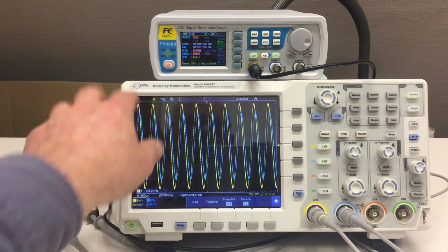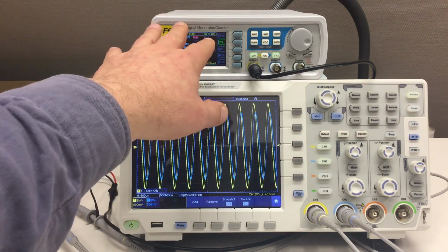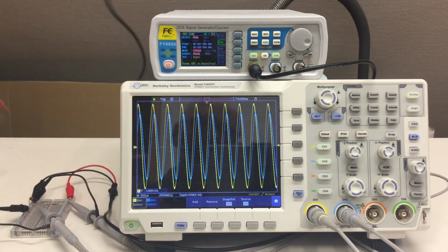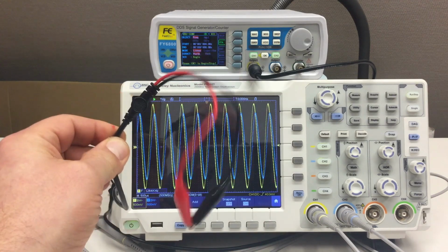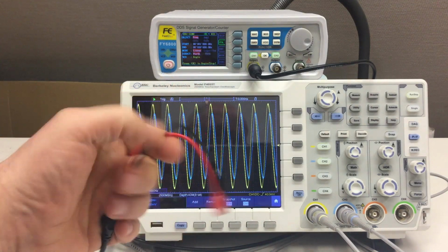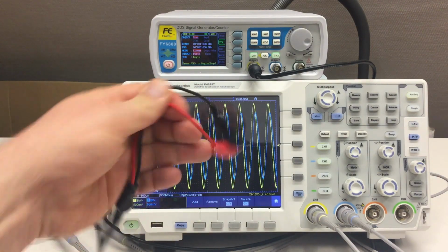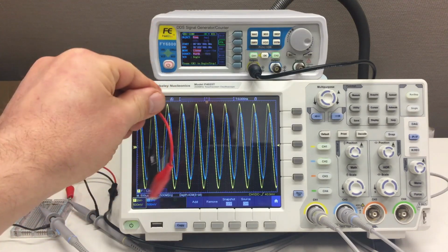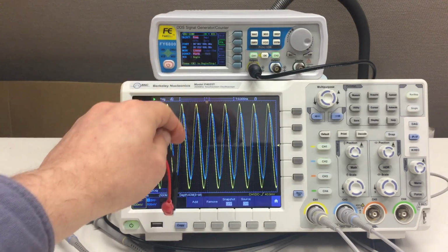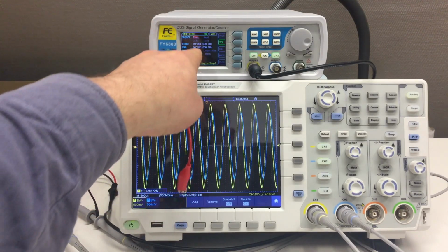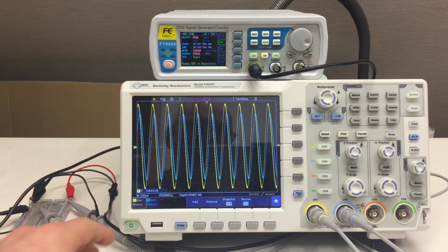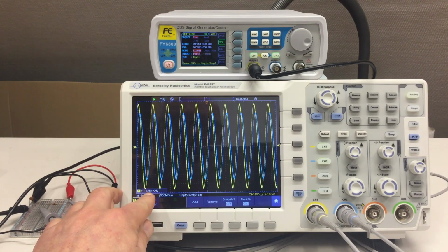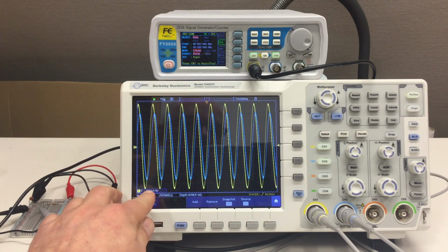So right off the bat, I set up the VCO here, and I connected a coax cable to the VCO input at the back, and I shorted it out to be sure I'm on 0 volts. And my start frequency, I will zoom in later maybe, is 1 kilohertz. And the thing outputs 1.26 kilohertz.